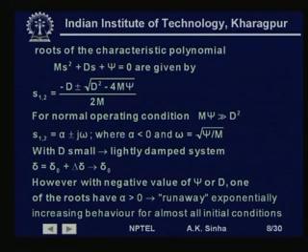That is what we said, that if either of these, that is, if this value psi becomes negative, then we get alpha as positive, which means the system is going to become unstable. That is, the roots come in the right half of the S plane, which shows instability, because the oscillations in this case are going to build up.